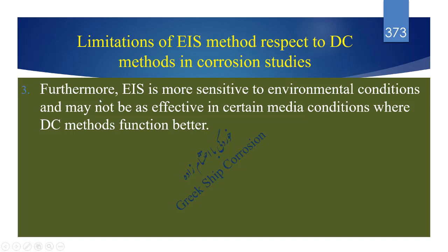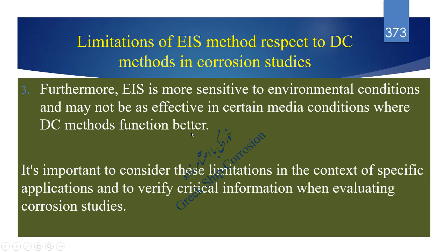3. Furthermore, EIS is more sensitive to environmental conditions and may not be as effective in certain media conditions where DC methods function better. It's important to consider these limitations in the context of specific applications and to verify critical information when evaluating corrosion studies.